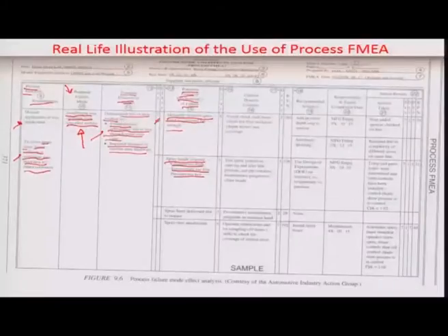There is a possibility that you may leave one vehicle because you have spent sufficiently longer time on another vehicle in front of it. So in order to line balance the situation, if the spray head has been clogged, the only alternative is that within the time cycle the operator has for one vehicle, he may dispense a thin layer which may get jeopardized later in terms of cracks or holes. So clogged spray heads may occur due to various reasons. For example, if the viscosity is too high, that may create such clogging.